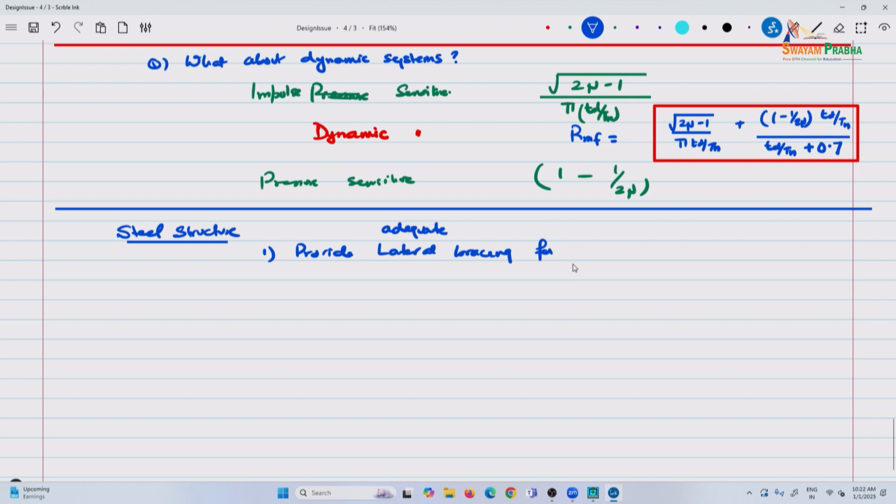Make sure you are not designing it, what I think there is another term that you use here, right? What is it? I think yesterday you were mentioning it. Laterally restrained and laterally unrestrained. It's the same thing out here, we call it laterally braced and laterally unbraced. So basically you are designing it for laterally restrained beam.